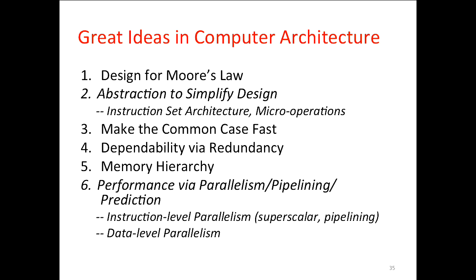Right? So, down at the core level, this idea of abstraction: in this example, we're writing x86 assembly code that gets turned into machine code. And that's the interface between software and hardware. However, as we saw in this chip, the story doesn't really end there because the hardware takes that x86 assembly code and actually turns it into something else internally. So inside the chip, it's breaking it up into something that looks like those RISC instructions you've been using in MIPS. It executes those, but completes them and commits them so it looks like it did those x86 instructions on the outside. So that's the idea of abstraction. We hide the fact that all this stuff is going on and make it look like an x86 on the outside because that's what all the software expects.